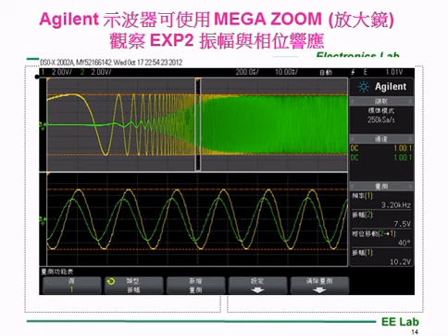On the Agilent oscilloscope, we could calculate the phase difference in both directions. Therefore, there is no need to change the original circuit configuration. Note that its precision is worse than Rigol.